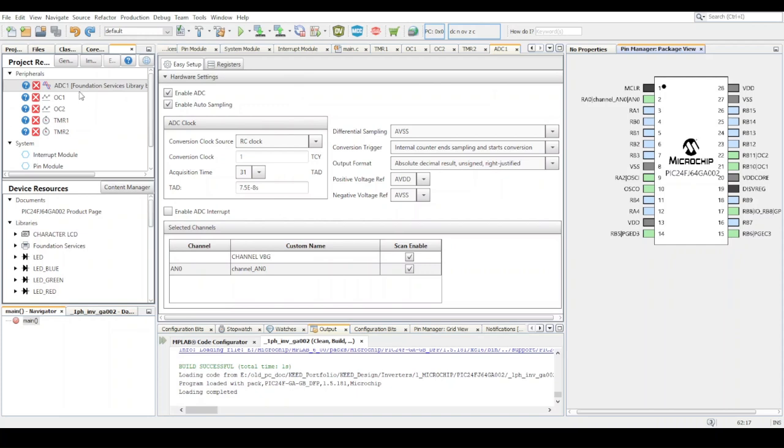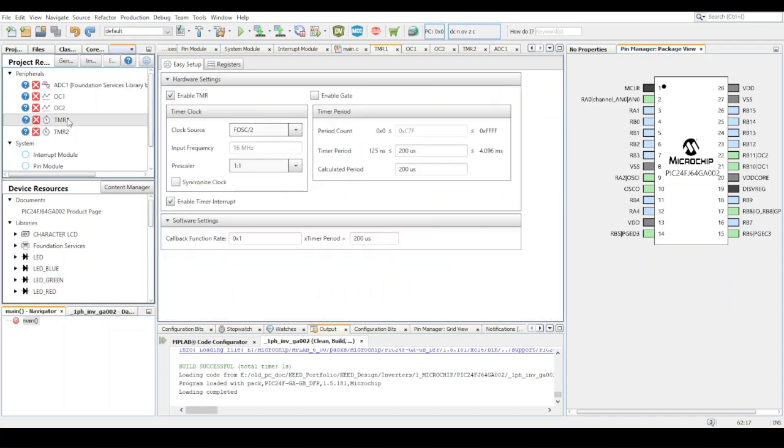Once you're done with that, we go on to the final aspect, which has to do with closed loop control. We're going to be utilizing a timer interrupt for closed loop control of the system. I'm using timer 1 for that, so every 200 microseconds there's going to be an interruption. Like I said previously, how many times you want to change the duty cycle is going to determine your timer interrupt time. Let me go back and explain it better.